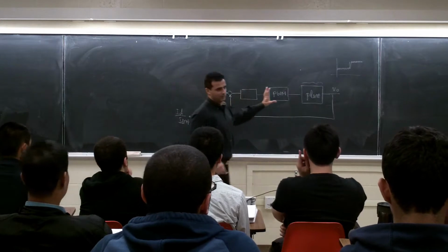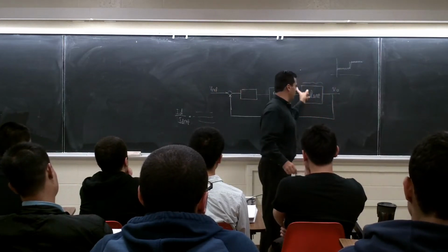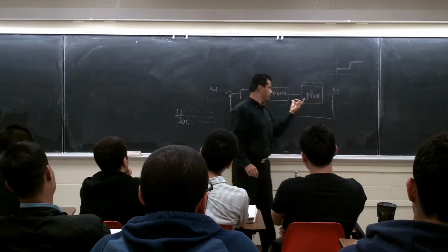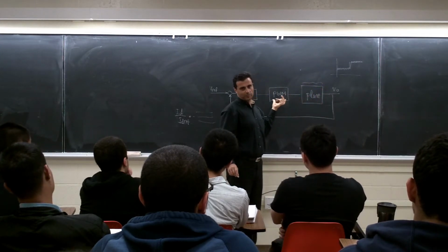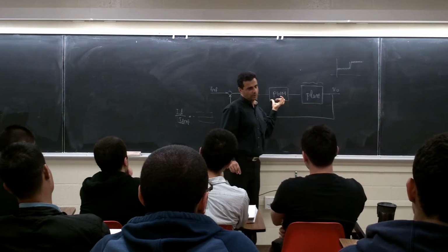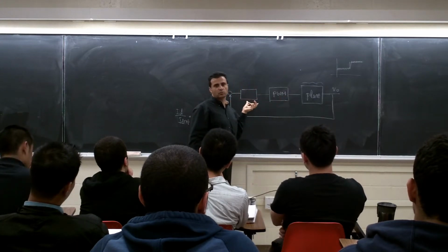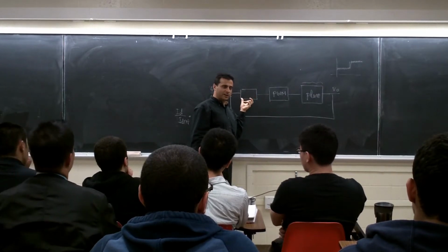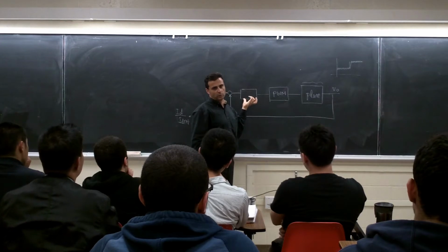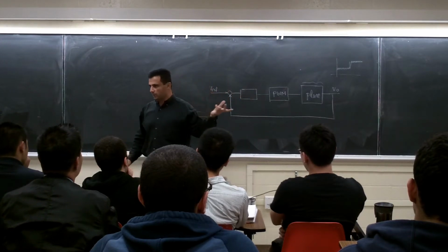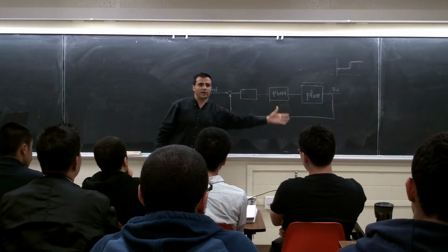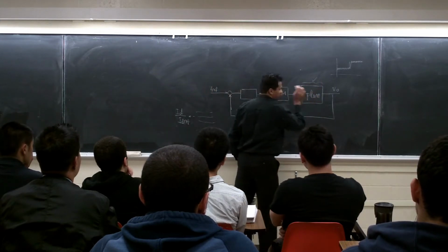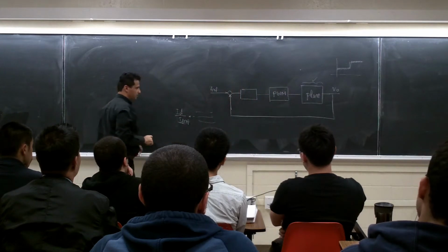Here we want to do the same. We want to use the transfer function of this plant. So you know what the transfer function is here. And after that, this one is a very simple block. I'll tell you what it is. The PWM generator. This one is either a PI controller, a PID controller, a second order compensator, different controllers. We'll talk about one or two specific ones, and we design this loop, and we say how to design this loop. Still, I need to complete this box here to see what the model for this one is.